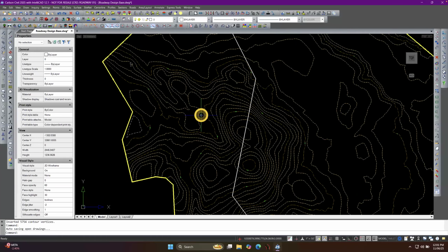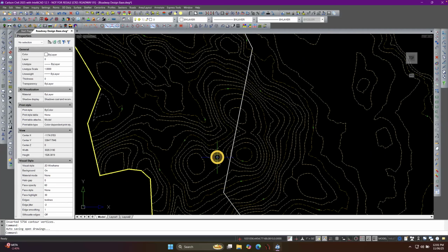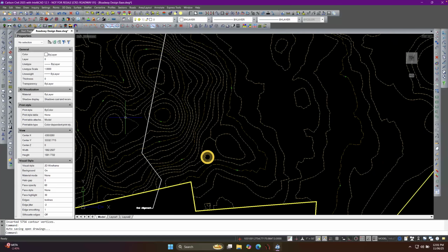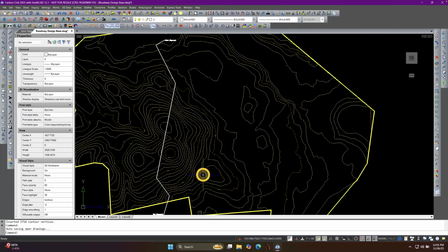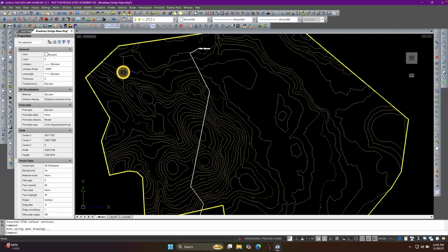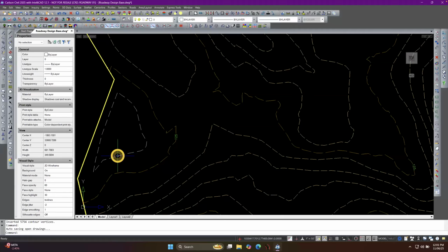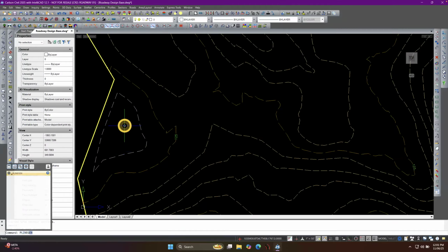And now you can see the density of the contour labels is more in terms of what I was expecting. Okay. Notice this line got generated with line type generation turned on because I did that command earlier, PLINEGEN, and that's just a setting in AutoCAD.